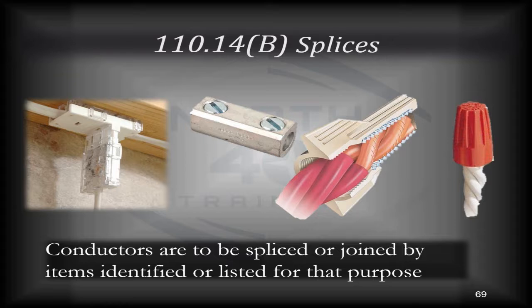Now, one thing you've got to keep in mind when you're looking at this stuff, when you're splicing, the basic rule to follow is when the product is finished being spliced and then reconnected, it must be mechanically sound, so you're not going to pull it apart, and it also has to be electrically secure as well, and it has to have the same insulation value that it had before the product was actually spliced.